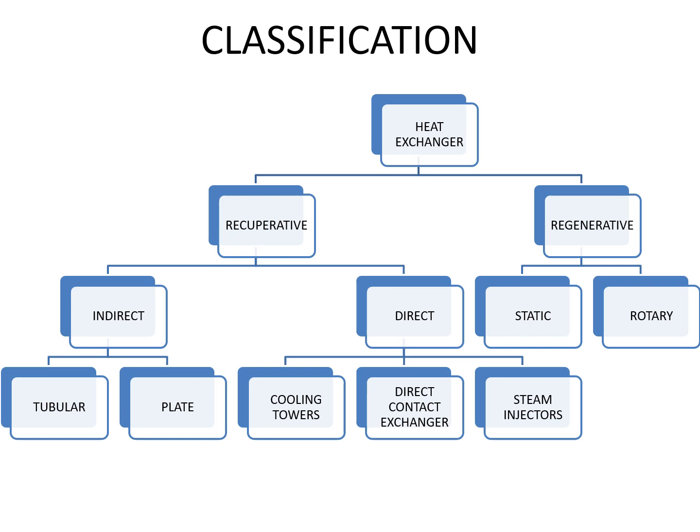And also a steam injector: you directly inject the steam into a liquid, into a medium. It is also a direct heating kind of heat exchanger. In regenerative type, there are two: one is static and one is rotary. We will not see much about this type of heat exchanger. We'll only target the tubular type of heat exchangers.